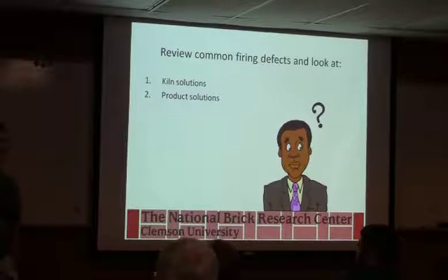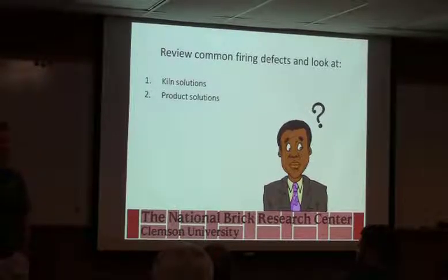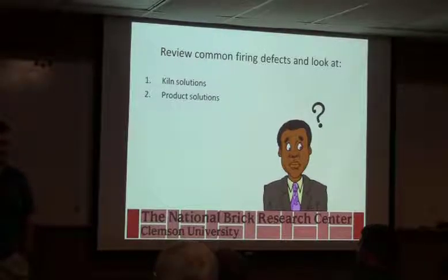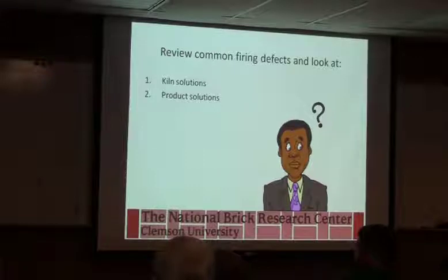All over the place. What you need to add, I guess the big thing, one of the things that I try to promote in the businesses that I've worked in is that when the business is running great, that's when you need to do the most work. Find out where everything is setting, what everything measures, go through all your burners, take all the mixture settings off of it, take all your temperature readings, and monitor the bejesus out of it. And then that way, when something starts to go off, you look at the picture now and say, what was it then? It's the same picture on the kilns.